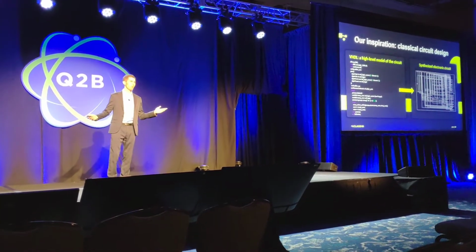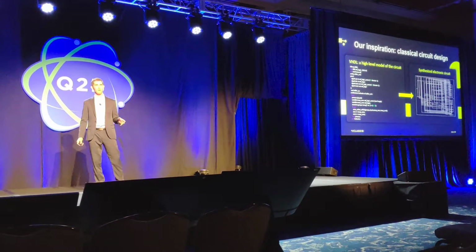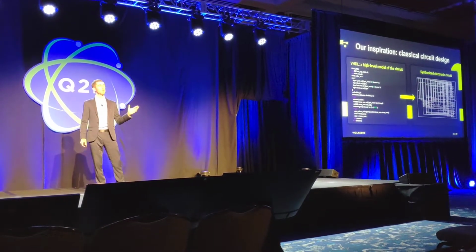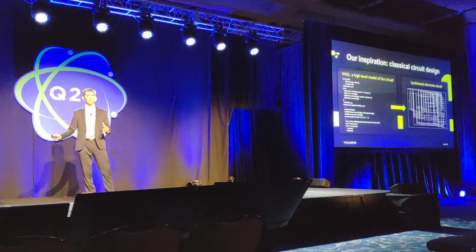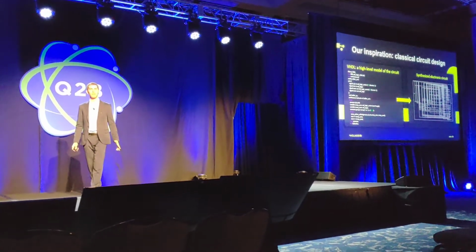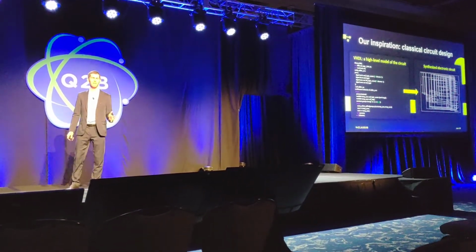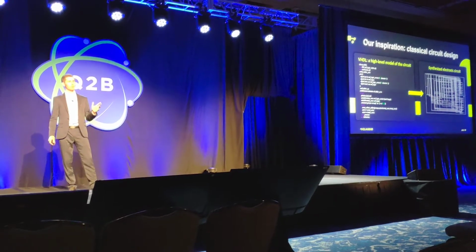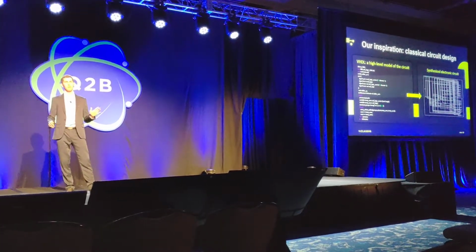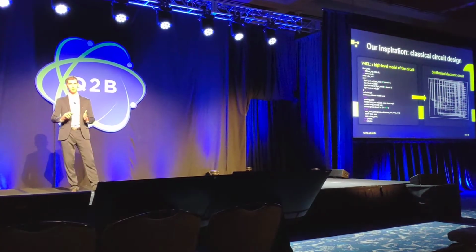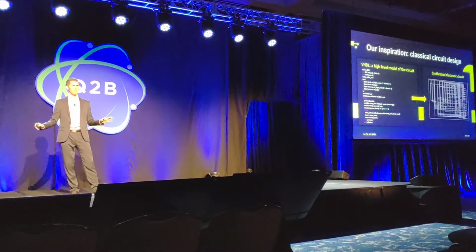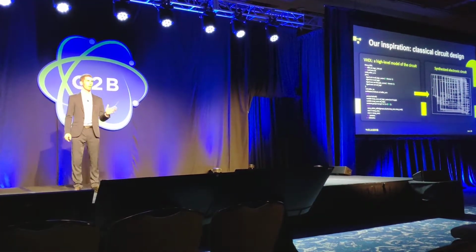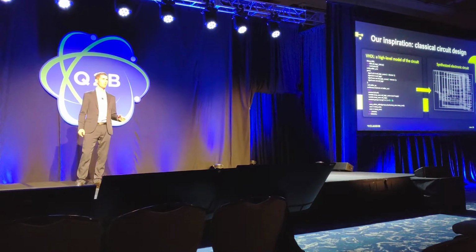And you don't need to, luckily, because in the classical world we have high-level modeling languages like VHDL and Verilog, and synthesis tools like Cadence and Synopsys, which allow the designer to focus on functionality, to define a high-level functional model of the circuit and forget about implementation, because implementation is automated by synthesis engines.